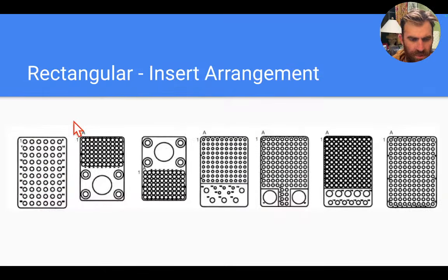And then for rectangular connectors, it's going to be a similar thing. It looks like from left to right, the numbers are increasing, and as you go down, they continue increasing. And you can see there are some different size contacts in the connector itself. So you could have a bunch of signal wires within the connector, and then a few larger pins for power and ground, or even Ethernet or coax within the connectors.